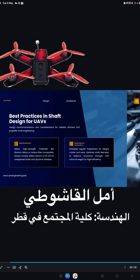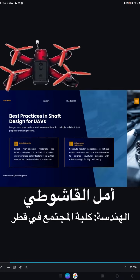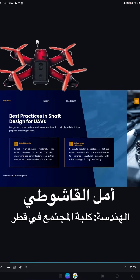Best practices in shaft design for UAVs. Use high strength materials like titanium alloys or carbon fiber composites. Always include safety factors of 1.5 to 2 for unexpected loads and dynamic stresses. Schedule regular inspections for fatigue, cracks, and wear. Optimize shaft diameter to balance structural strength with minimal weight for flight efficiency.